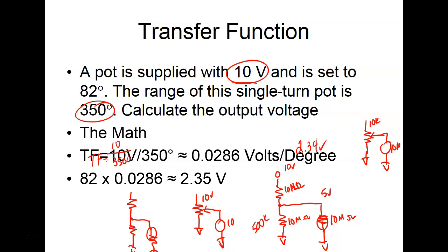You understand? So what we're saying is that for a pot to work, the load that this feeds into has got to have a really high input resistance. If it does not have a high input resistance, then we've got a problem. So that means if I had a 10 mega ohm pot and you put your meter across that wiper, then all your calculations are going to be out of whack. But this would be another advantage of using a pot that has a lower resistance, right? You understand? So it wouldn't have near as much loading effect. We call it the loading effect.